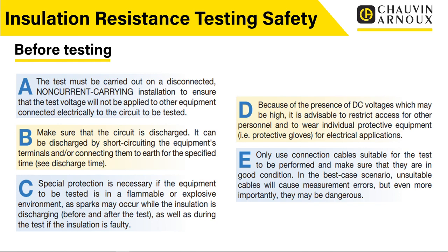It's the same when you're actually carrying out tests on circuits. Those circuits have been operating at mains voltage, so if there is any capacitance in there, capacitors, things like that, they will actually store that charge. So before we carry out the test, it is essential that we actually discharge. We make sure that the circuit under test is fully discharged.